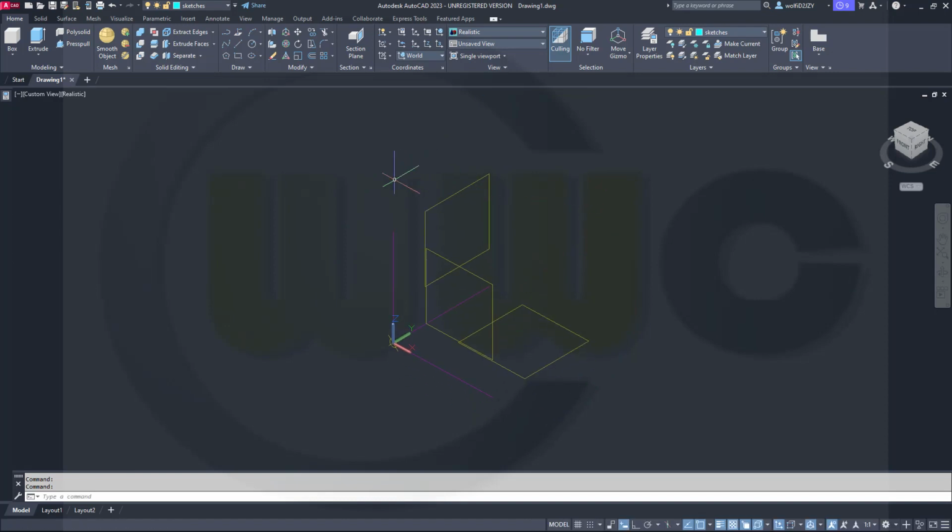First I want to create some reference points. So, go to Draw, go to Points. One should sit at 110,0, another one at 0,-50. Let's take a look.